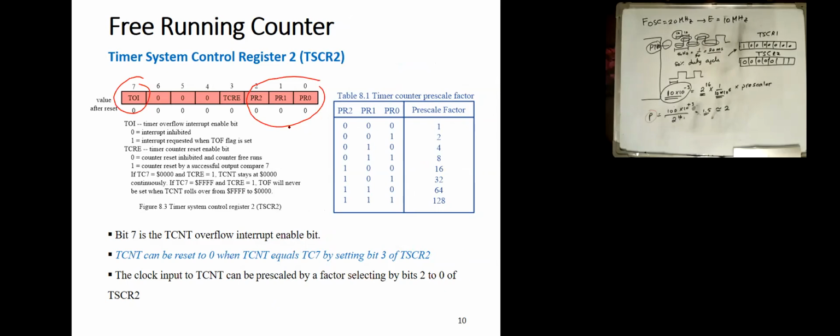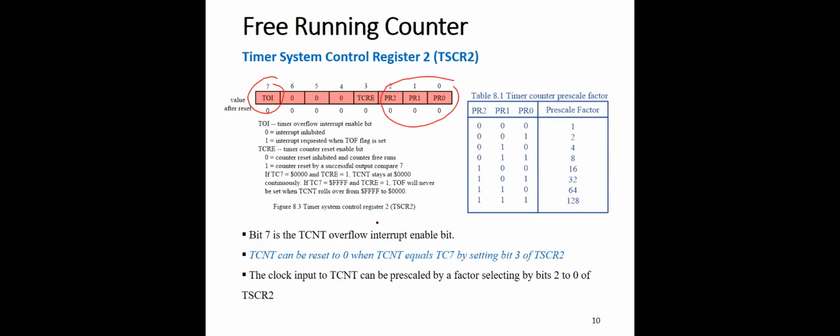And finally, for the prescaler that we chose, which is basically 2, the value to be stored in these bits is basically 0, 0, 0, 1. Hopefully I did the math correctly. And this is what we need to do with these two registers.